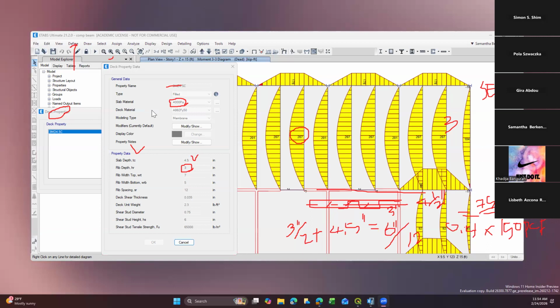You understand this, right? And here you see the metal deck default weight. So maybe we can add 2.3. So total slab weight is 77.3, right? 77.3. And still, I don't know what sizes we are ending up, but we can roughly calculate it. So tributary width is 10.